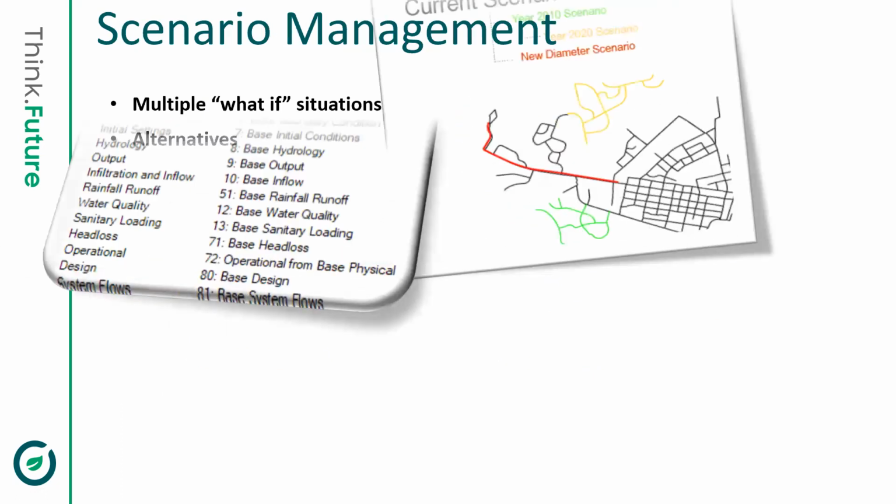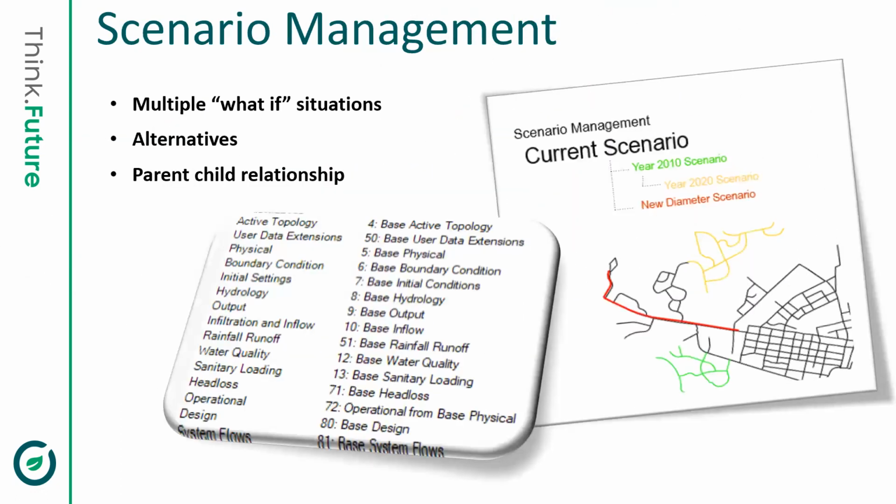Then we have the scenario management concept also within this software. Scenario management is one of many project tools available in the different OpenFlows products. A scenario allows the user to calculate multiple what-if situations in a single project file, and the user, or we can say the engineer or consultant, can try several designs and compare the results, or can also analyze an existing system using several different input alternatives and compare the results.